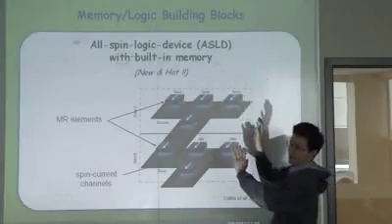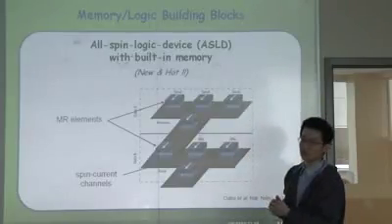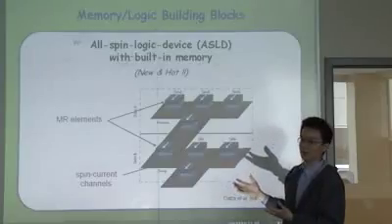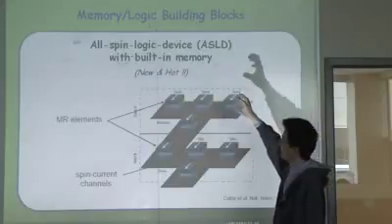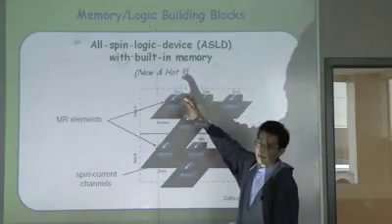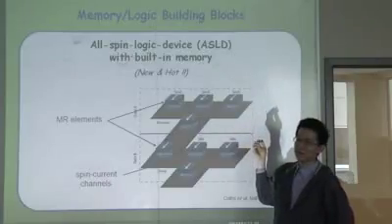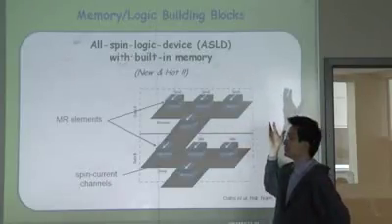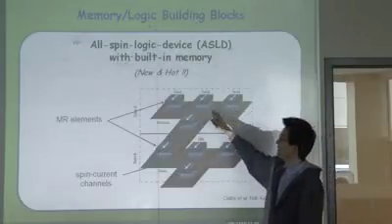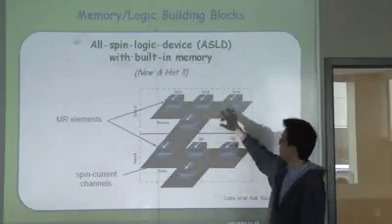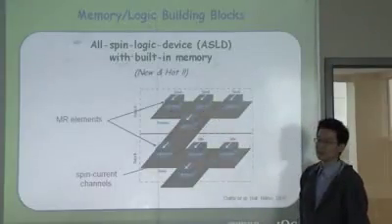So basically, by combining all these features, you can perform all these 4 fundamental logic operations, which means you can do everything else. So they are capable of performing all logic operations, and each of them is also a memory of itself because they are MTJs, so they are basically MRAM on their own. So you have a computer with logic, with the memory, everything together, and mediated by spin current, all the communication. You combine all these channels for different operations.